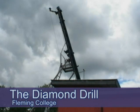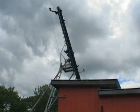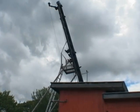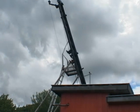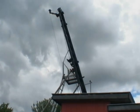The diamond drill is not typically used in water well construction, as it is primarily for mineral exploration in hard rock formations or, in some circumstances, monitoring well construction. However, this system can be used to construct water wells in remote areas where no other suitable equipment exists. The disadvantages include a small diameter hole with small reservoir that is not well suited to pump applications.